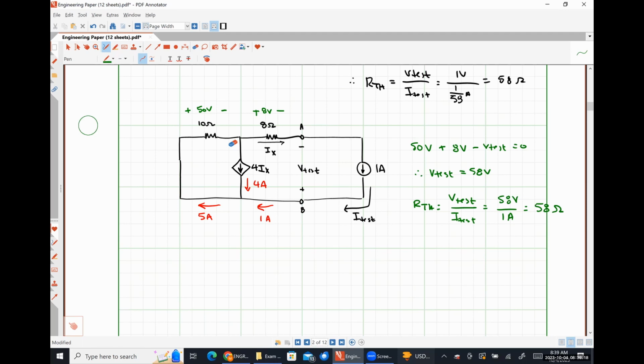To find our Thevenin resistance, that process changed pretty significantly because we can no longer simply look in through our terminals and apply resistor combination techniques, because there is a dependent source messing up the application of those techniques. So we have a couple of different options. We can choose to take the ratio of V Thevenin divided by I Norton to get our Thevenin resistance, or we can apply a test source method to find our Thevenin resistance directly. Yes, ma'am.